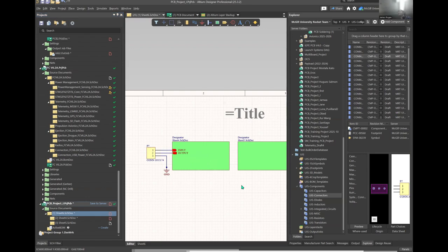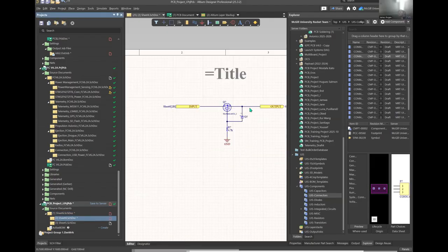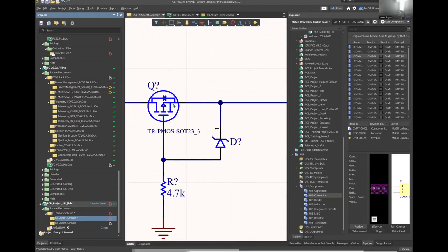Oh, that's it. The diode. From the other side, it was as if the diode was acting as another input. Yeah, exactly. Altium doesn't know that neither of these pins are sources of anything. They can't input any energy into this. Like it sees the diode as if it was another input. It just sees, okay, there's 2 pins on this net. That could be fine. But if there's only 1 pin, Altium knows, okay, that's probably not okay.